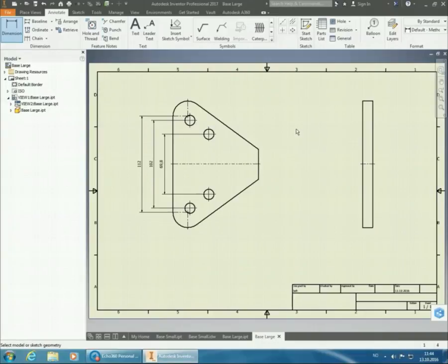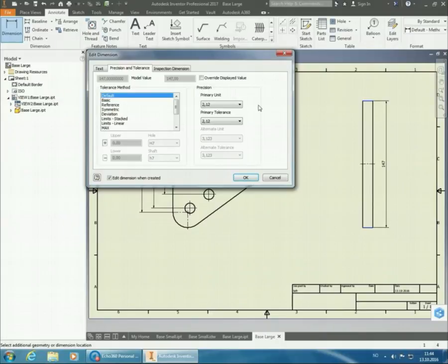Now, even though we're going to give the radius of the edge here, it might be nice to actually give the total width of the part over on the other side here. So we'll give it from here to there, being 147. But this one we need to put in as a reference dimension because it's dependent on the radius of the rounded edges. So we need to mark it as reference so that we get the parenthesis around it.